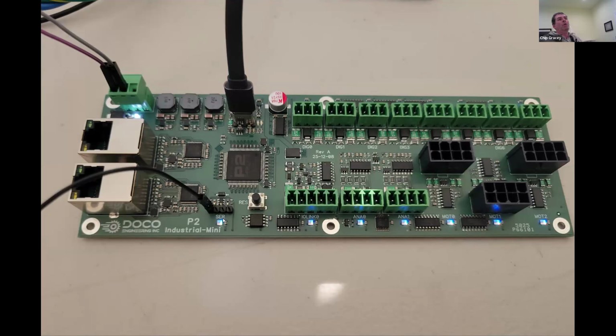But ultimately, what I needed was some kind of little state machine that can give me the next state for the LED output, right? If you look at the bit protocol, it's a serial protocol for these LEDs. You have a bit period of about 300 nanoseconds. You want to go high, that means start. 300 nanoseconds later, you output your data bit, which is going to be high or low.